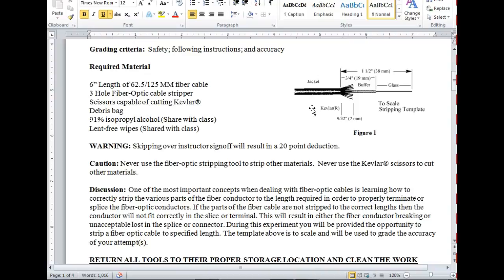And you'll constantly be doing what? Pushing it back in. But now, since we've got it tied in a knot, it's not going to go anywhere. So now you can strip it and all kinds of stuff, which would simulate having a long cable. So when y'all do this lab, the first thing you're going to do with the end that you're not working with is tie it with a knot. That way you can cut it, you can strip it, and the conductor won't come out on you.